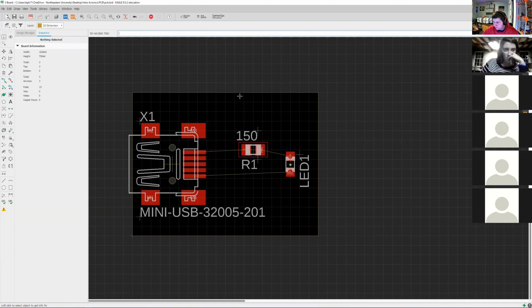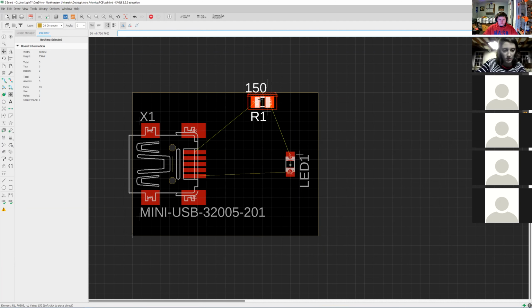Yeah, so I've done this just a little bit over the edge so that, like, I don't know if you noticed, but when I move something too close to the edge, it lit up with these cross-hatched warning areas. That means you've broken one of the design rules. The design rules basically tell you what you can and cannot do, because only certain things are actually manufacturable.